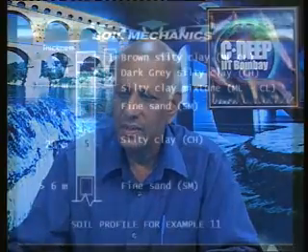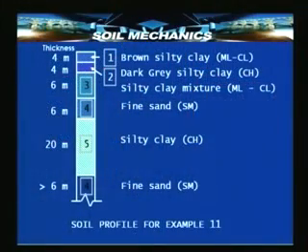So this is the subsurface profile. There are 5 layers. The first layer is a silty clay layer, the second one is also a silty clay layer, the third is a mixture of silty clay, then the fourth is sand, the fifth is silty clay, and once again the next layer below the silty clay layer is sand. That means it is a doubly draining layer.